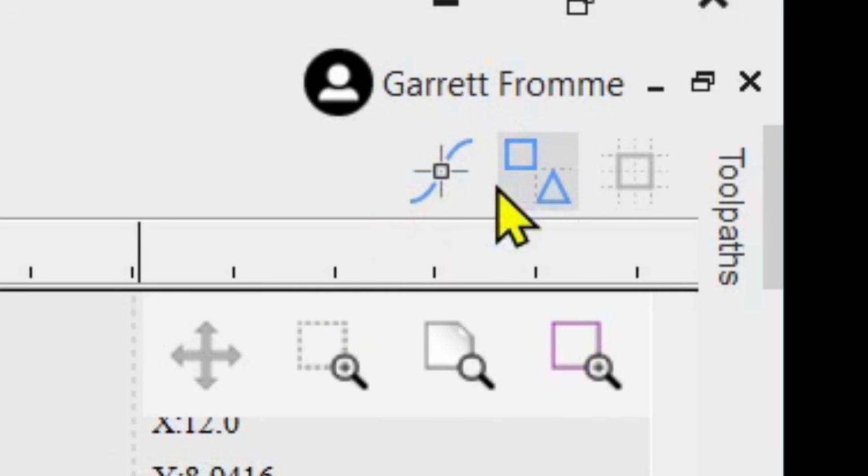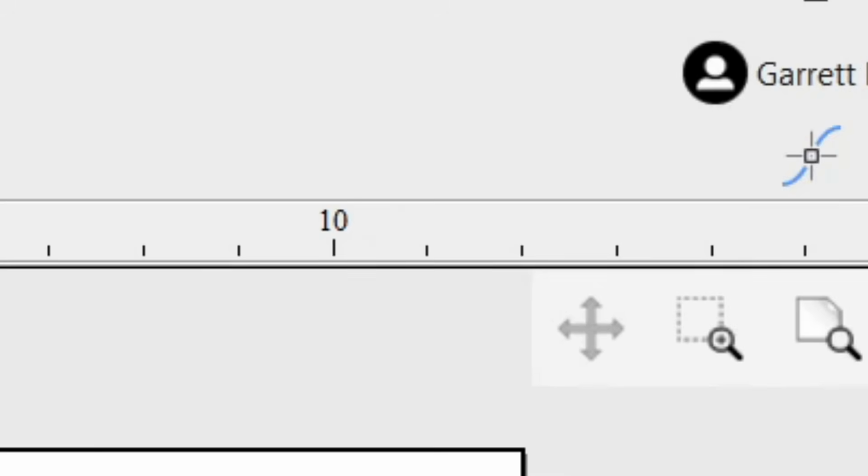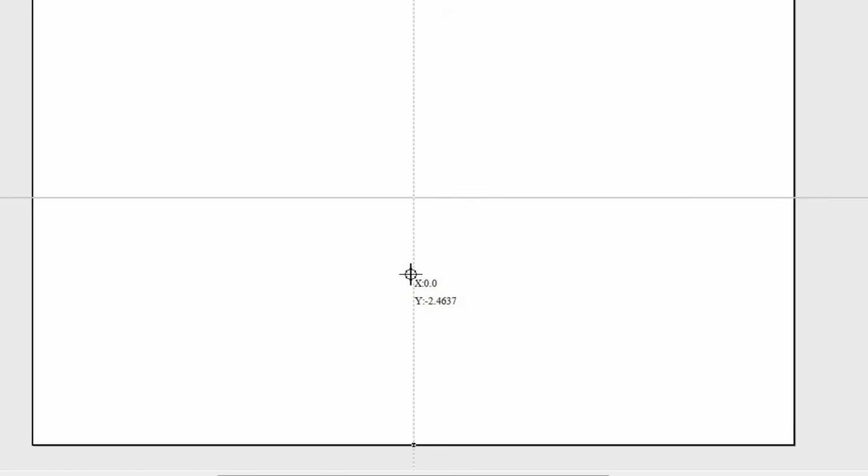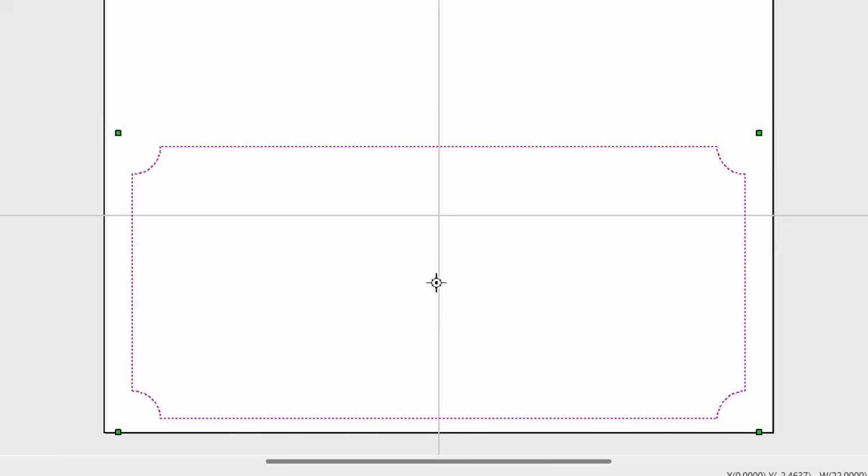What this cursor change is telling me with the number below it is that when I create this rectangle, it is going to start right at the center line of the project, and it's doing that because our snaps are turned on. That's all the way up here. Remember, we talked about this. We want these two buttons turned on. The one other thing I want you to do is over here, I want you to set the anchor point to the middle. So now we're going to come over, we're going to let it snap somewhere just below here and click once with the mouse.